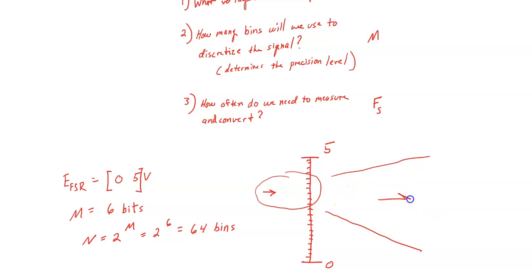This voltage value might come in. And once we've discretized that 0 to 5 volts into bins, we might have one bin value here, and one bin value here, and one bin value here, and those continue going up and down. Let's say this comes in and it's 3.48613 dot dot dot.